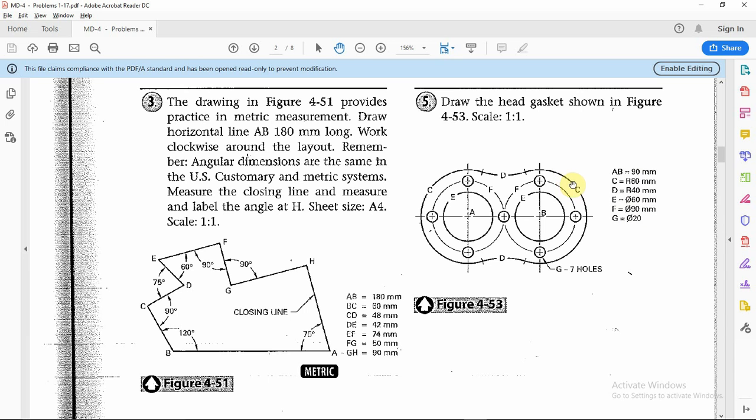If it is an arc, partial or part of a circle, then they're going to give you a partial dimension. Basically, they're just reducing it down to the radius. So, simply put, if we have an arc, they are given size-wise with the radius. If we have a full circle, that is given dimension size-wise with the diameter.